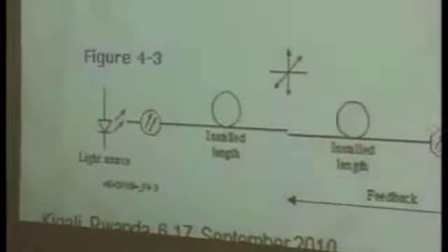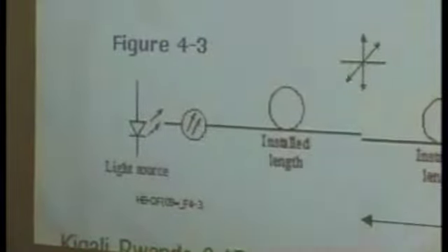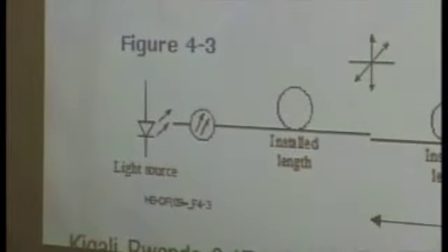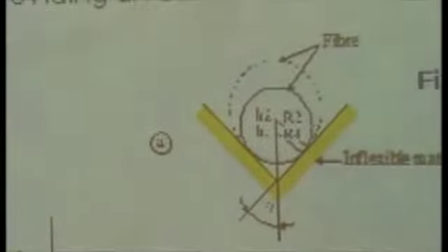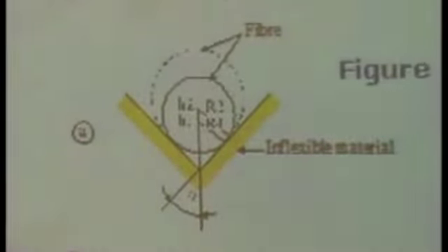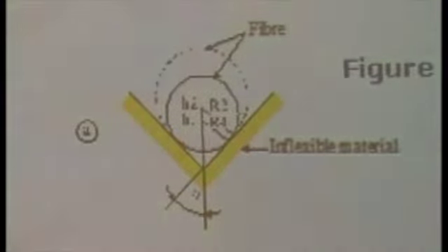The splice machine minimizes the splice attenuation, and this way focuses on the core or cladding of the fiber, aligning them, or optimizing the transmission line through the fibers and providing an estimate of the optical splice attenuation after the splice is complete.